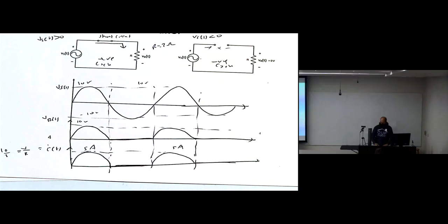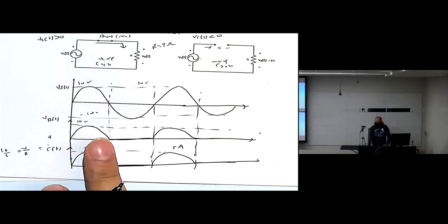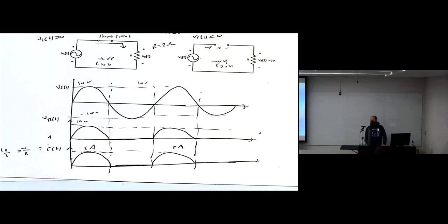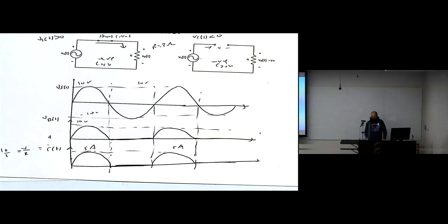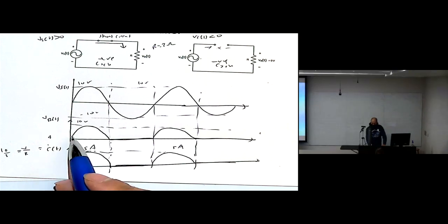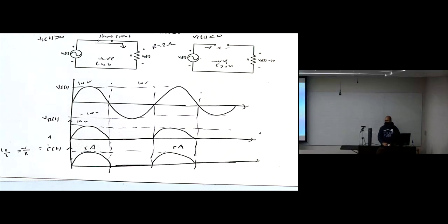So now we see this equivalent circuit. Do we see any DC value? This is not actually DC. So a half-wave rectifier alone is not efficient to be a DC. Even if it's an AC to DC converter, here the average value will not be 0. So I can get somehow, but it's not enough to say we have a rectifier, or that we are converting efficiently from AC to DC.